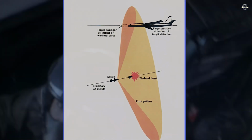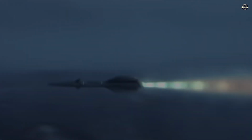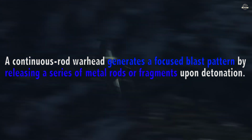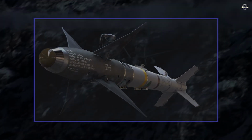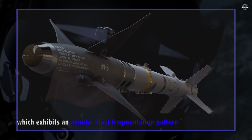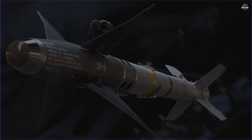anti-aircraft and anti-missile missiles. Unlike conventional explosive warheads that generate a spherical blast, a continuous rod warhead generates a focused blast pattern by releasing a series of metal rods or fragments upon detonation. An example of this type of warhead is the AIM-9 Sidewinder missile, which exhibits an annular blast fragmentation pattern, dispersing in a large circle upon explosion, effectively penetrating the target.